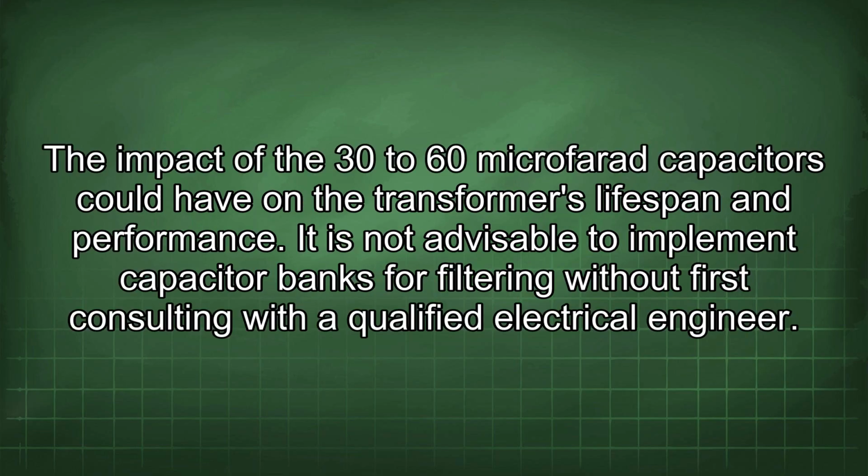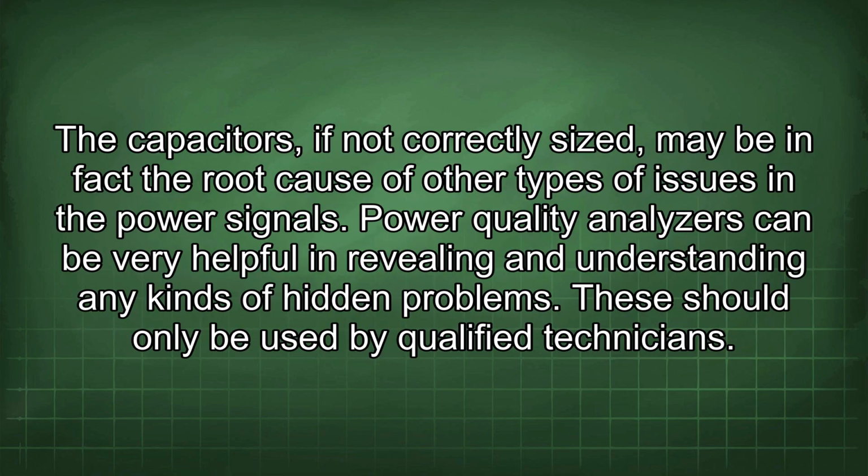The impact that 30 to 60 microfarad capacitors could have on the transformer's lifespan and performance. It is not advisable to implement capacitor banks for filtering without first consulting with a qualified electrical engineer. The capacitors, if not correctly sized, may in fact be the root cause of other types of issues in the power signals. Power quality analyzers can be very helpful in revealing and understanding any kinds of hidden problems. These should only be used by qualified technicians.